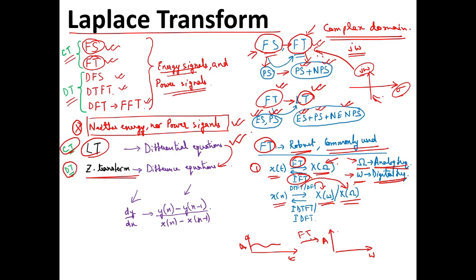Now if this is the case, then our life will be much easier, and that is what the first instances of digital filter systems were considering. So they took analog systems, they took the characteristics of that one, they applied some transform to get into the Z transform. So there has to be some connection between the Laplace transform and Z transform, otherwise how will you apply that transformation? It is not possible, right?